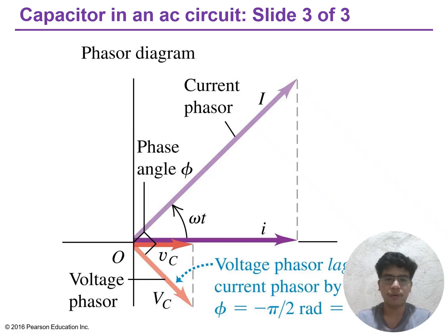This temporal relationship is inverted compared to inductors and reflects the fundamental mathematical relationship between the charge accumulation, or the voltage, and the charge movement, or the current. Current represents how fast charge is moving onto or off the capacitor plates, while voltage represents how much charge has accumulated, making current approximately the time derivative of voltage.